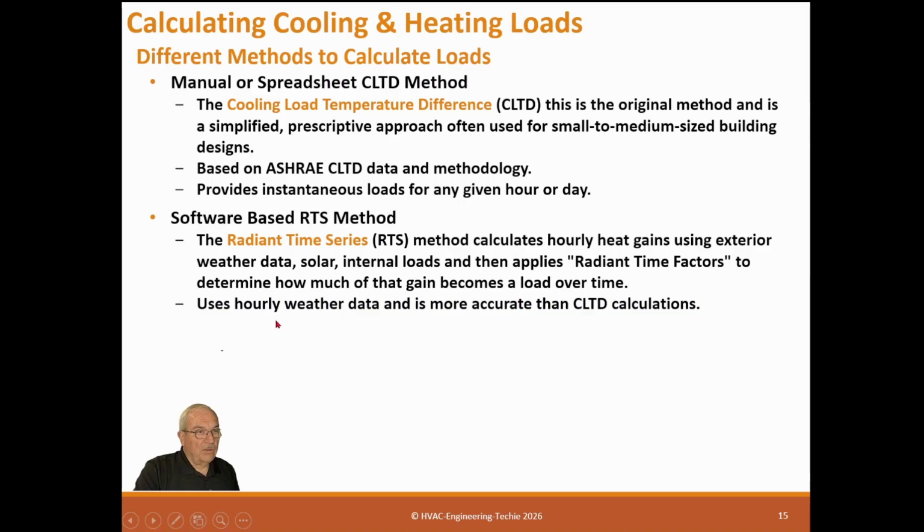They use that hourly weather data and it is more accurate than the CLTD method. It does have more method because it tracks the energy usage over time, whereas the first one, the CLTD, just says temperature difference. It doesn't actually track that change or the mass storage of the heat in the wall, which the RTS does. So it doesn't mean that this is inferior to this. It just means this is a little more accurate. But this is obviously going to be done with a computer.